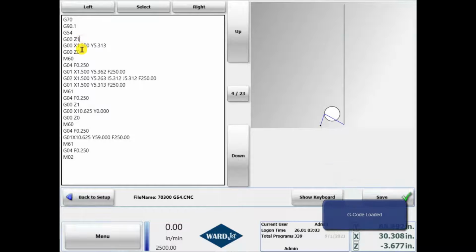There are a couple ways of doing this. For example, Z heights can be based off of the top of the table. Oftentimes, especially for water only cutting, we'll set the Z position for the work offset at the top of the table, and then in the CAM system, based on the thickness of material selected, these Z values will change.